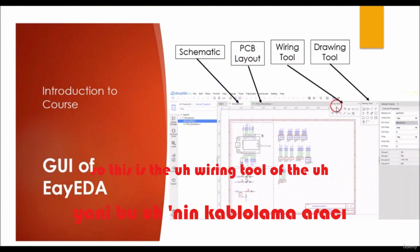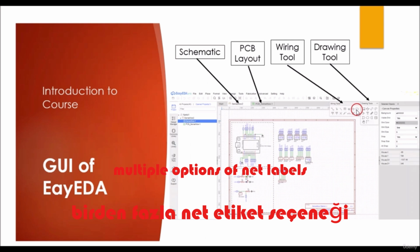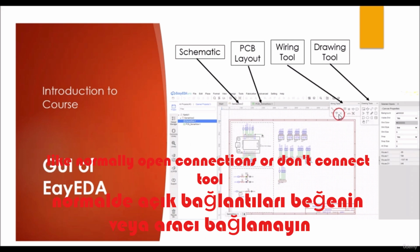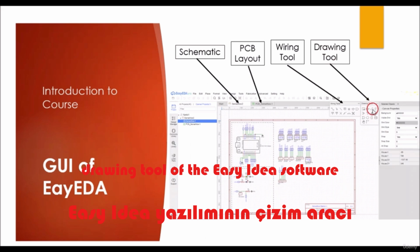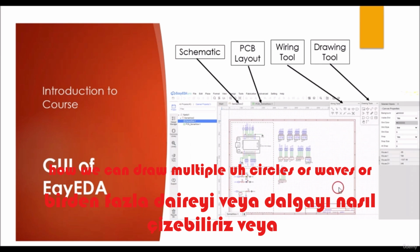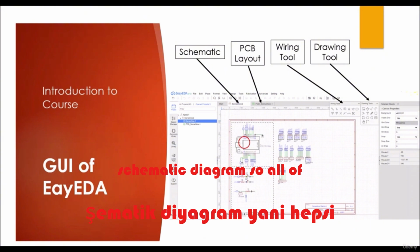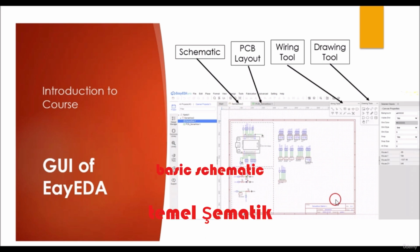So this is the wiring tool of the EasyEDA software, in which we have multiple options of net labels, connections, not connections, like normally open connections or the don't connect tool. Next is the drawing tool of the EasyEDA software, which also contains multiple options for how we can draw circles or waves or different types of texts or rectangles in the schematic diagram. So all of these tools are very helpful in designing the basic schematic.